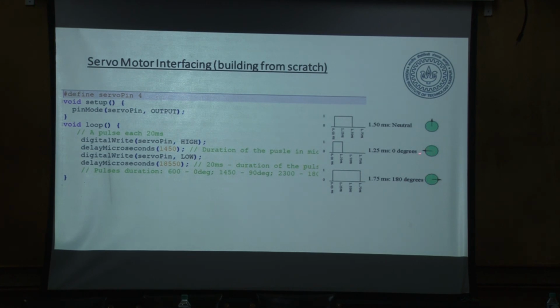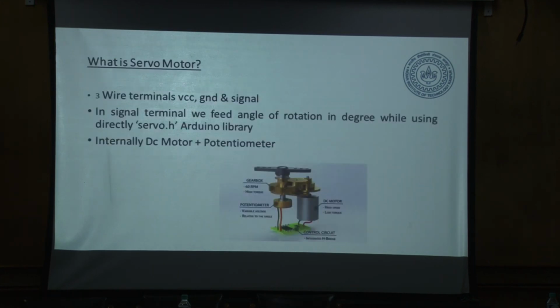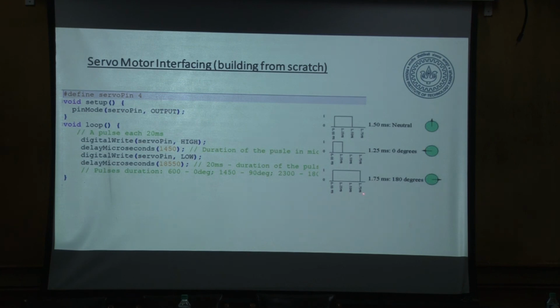So this part is this part. So that part is this part. Okay. So what it basically means is that if you give a duty cycle this much, then it will go and stop there. Okay. If you give 0 degrees, it's on the other side, so 0 to 180 degrees, and you can control any point in between wherever you want it to stop. Accuracy is not bad; it's quite good. It's about 0.2, 0.3 degrees. So it's quite good for doing experiments.